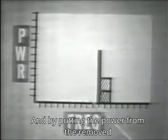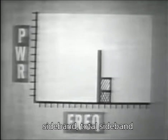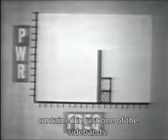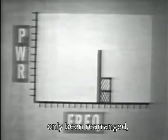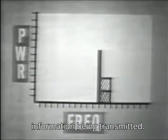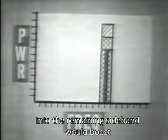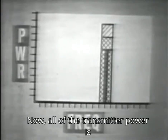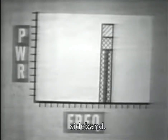And by putting the power from the removed sideband into the remaining sideband, total sideband power is restored and is contained in just one of the sidebands. Well, so far, the sideband energy has only been rearranged with no resulting power gain in the information being transmitted. However, putting the carrier power into the remaining sideband would boost the sideband power tremendously. Now, all of the transmitter power is located in one sideband.